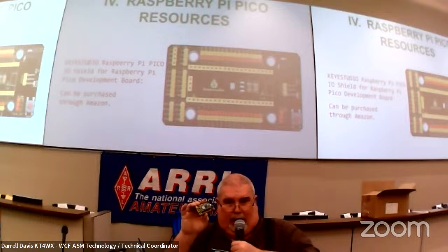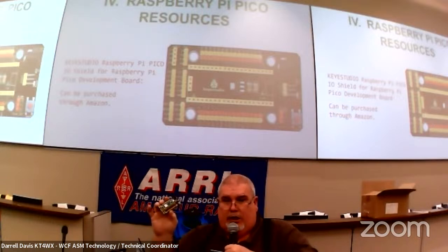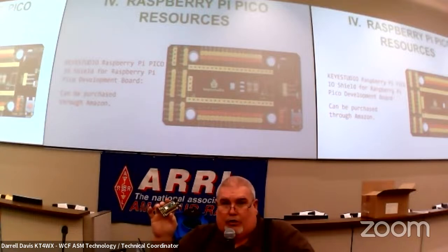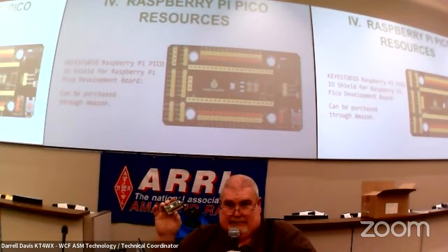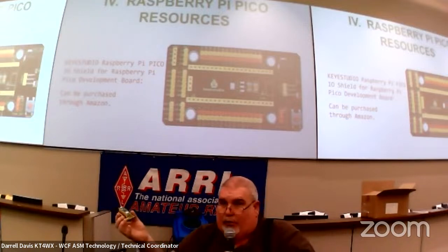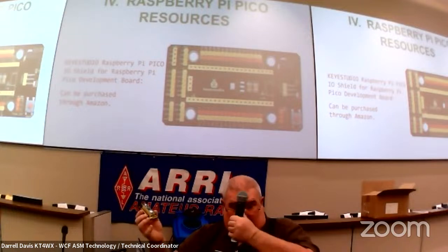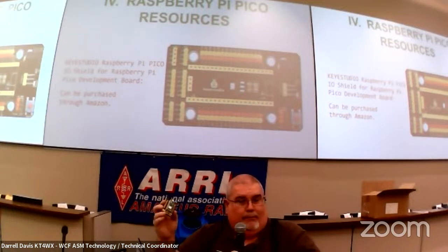By the way, a caution on the Raspberry Pi Pico ports. Like most modern microcontrollers, don't put over 3.3 volts into it. Some controllers only handle 1.8. That's modern microcontroller design. So if you use the ports, you have to buffer them. And if it's a device that has 5 volt TTL voltage levels, you'll have to have a buffer chip. It will not like it if you go over 3.3 volts. You can damage the microcontroller.